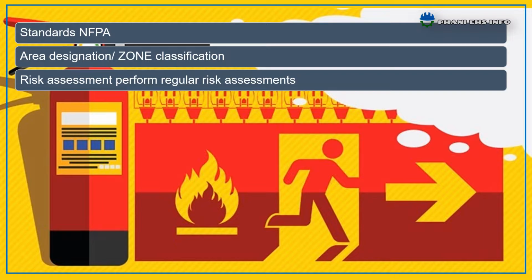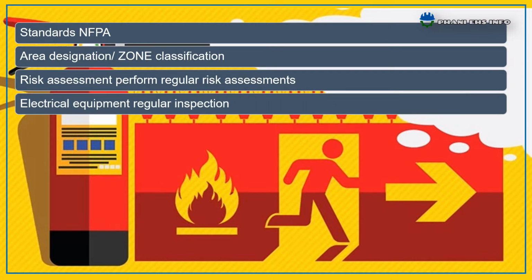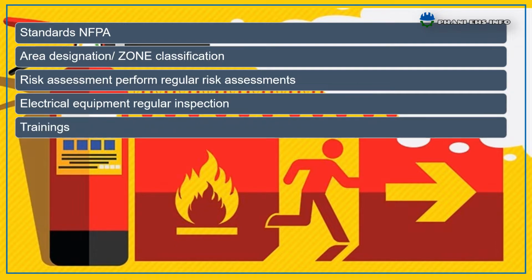Identify and resolve deficiency sources within the facility that emit heat or are combustible, flammable, or make the building more susceptible to fire. Electrical equipment: regular inspection and maintenance by qualified electricians. Prohibition of makeshift installations. Regularly train staff on fire prevention practices and perform regular fire drills.